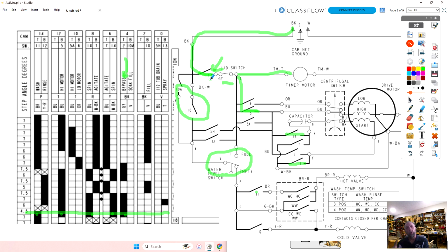One can't be opened because the machine that has a lid lock, the transmission does not have a mechanical brake. When you lift the lid switch on a direct drive washer, what happens? You see that basket go, and it stops. That's a brake mechanism.